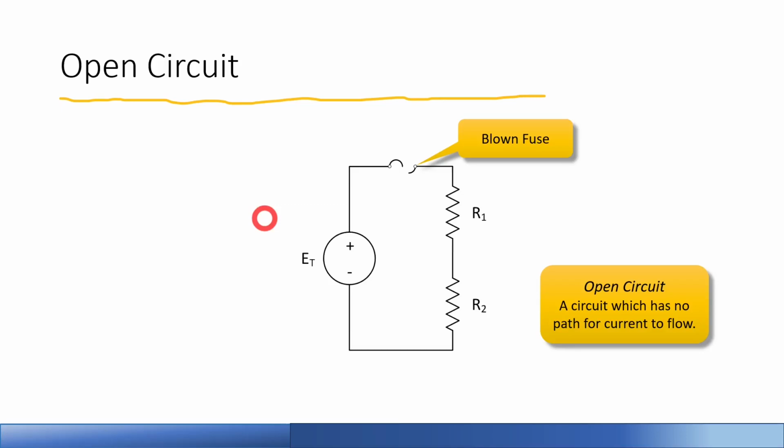Okay, so in this case, once that fuse is blown, the power supply will no longer be serving current to the resistors, and there will be no path for current flow, and so therefore we won't have any voltage drop across our resistors or any power dissipated across those.